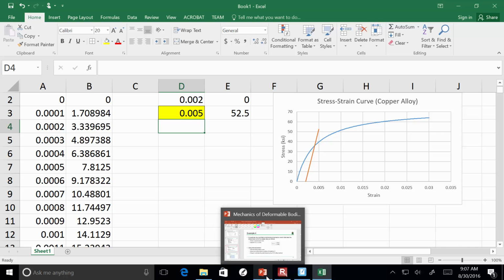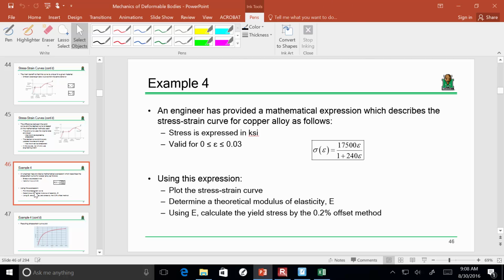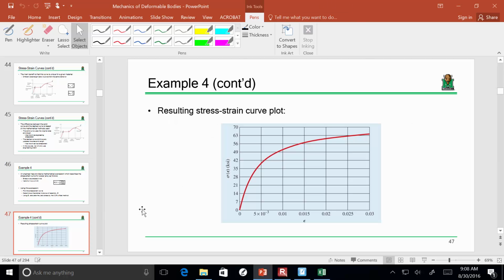All right. So I've given you some data where you actually need to take it and plot it and make some interpretations. Now, I'll preface this by saying the data is in force and deflection, so you have to turn it into stress and strain. You know, divide the force by the area, divide the deformation by the original length, so that you're on the same page. Okay. I've got that. I'm going to post that online. It's going to be due next week.